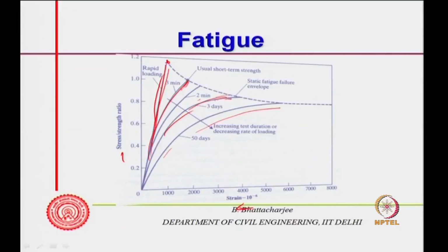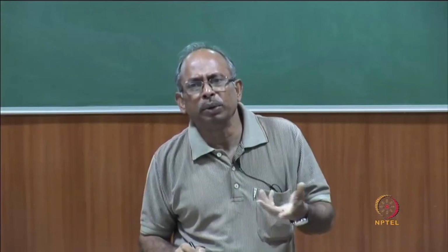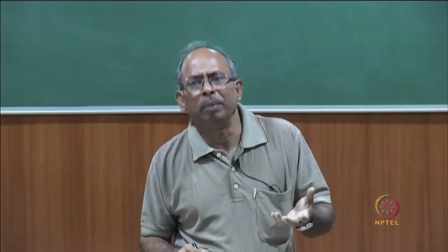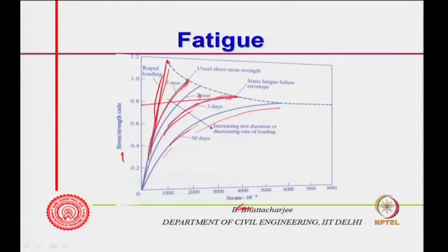If you take 3 days, then you find that you keep the load for 3 days. So, at 80% of the static load it will fail. Keep the load for 3 days, it might fail somewhere around 80%. I mean, this is a notional thing, one cannot take it for granted all the time, the values might differ from test to test. And if you keep it for 50 days, it will actually fail somewhere there.